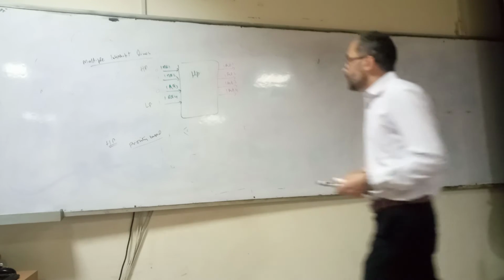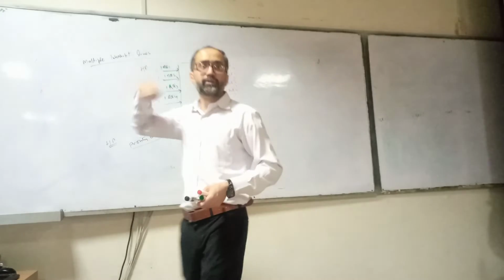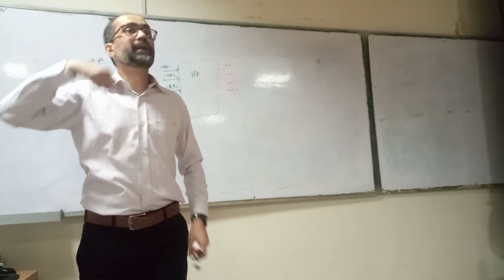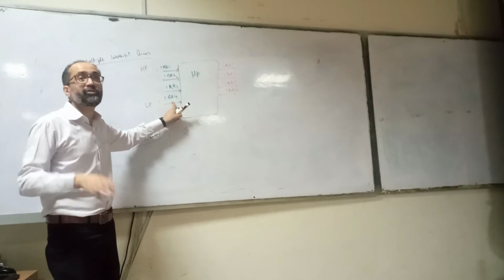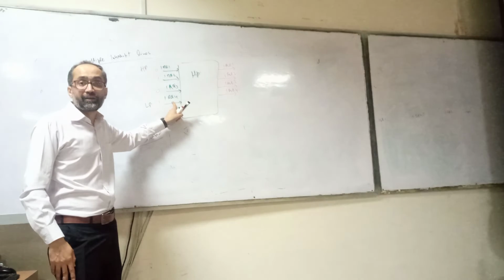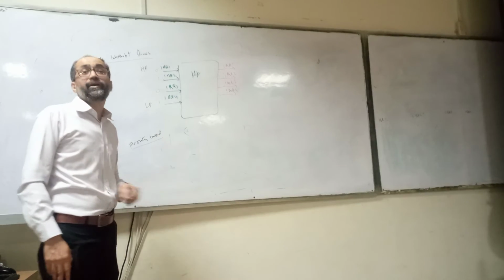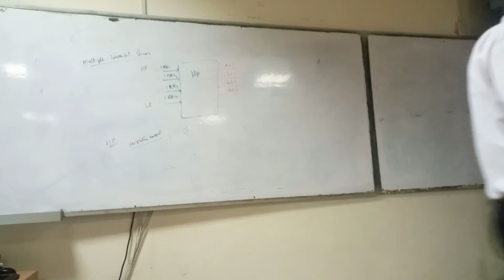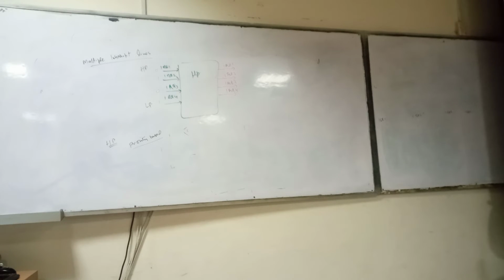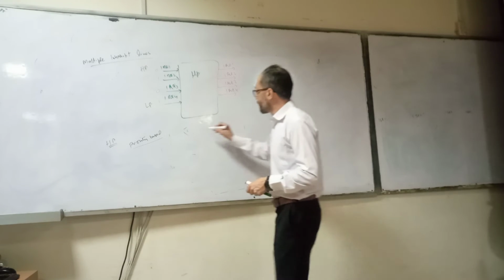Let's assume the two higher priority devices generate interrupts again and again, and IRQ4 is also generating an interrupt. It will never be serviced. So it causes starvation. It may be unfair to some of the other devices. So we have another mechanism that we call rotating priority.